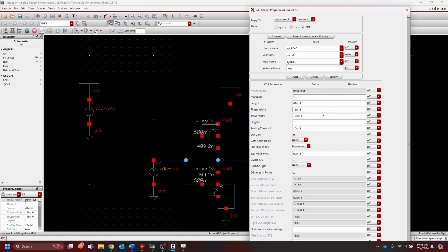Okay, so one other thing to notice about the width is that if we try and increase it just slightly, like 121 nanometers, it doesn't like that whatsoever because it can't control it down to 1 nanometer. Potentially, if we increased it up to 140, then it does like that. If we tried 135, it's okay with that. If we try 133, for example, it doesn't like that. So it looks like it's in 5 nanometer steps, so you can increment it. So maybe we could do 125 nanometers.